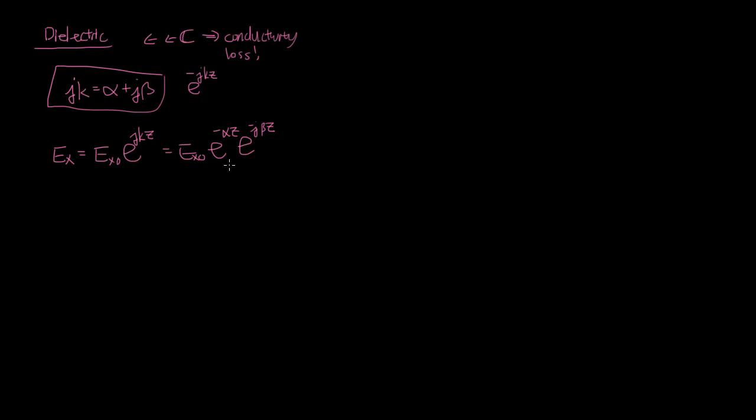So let's turn this back into instantaneous form. First of all, what does this do? This becomes attenuation, right? Because I have this alpha component here, my amplitude decays as I propagate in the positive z direction, and the rate of decay is this term alpha. In other words, let's put this back into its instantaneous form. In the textbook, they sometimes use italics to describe the instantaneous form, but another way to make absolutely known that you're talking about the instantaneous form is to explicitly specify that it's also a function of t.